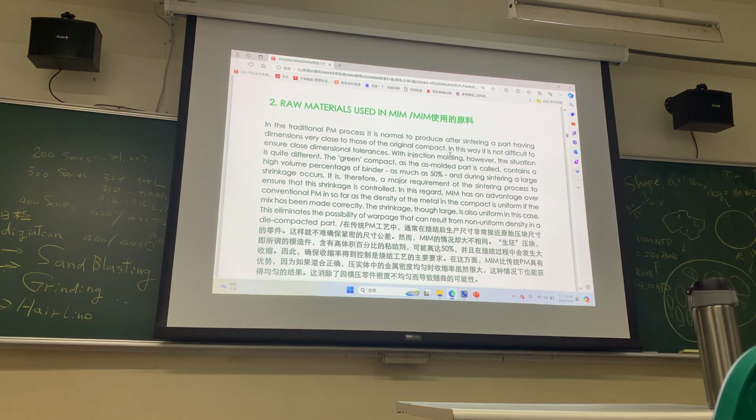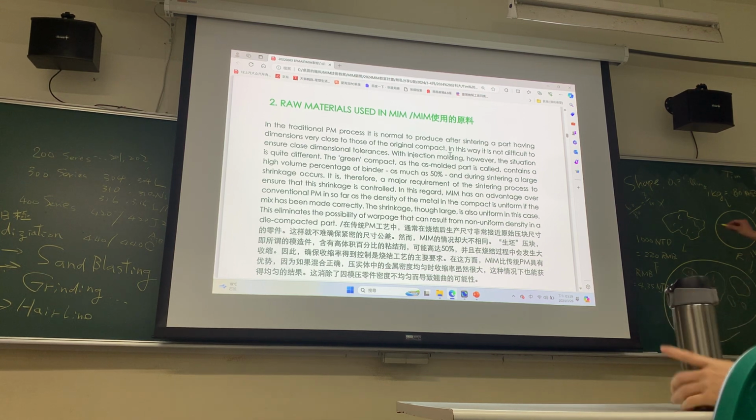If the surface is smooth, it's good for molding, but easy to segregate binder and powder. If we use this one with no good surface, the binder can catch easily. So this is interesting. So we choose this one. We just adjust the recipe of the binder. We can make good flowability and viscosity, better than this one.